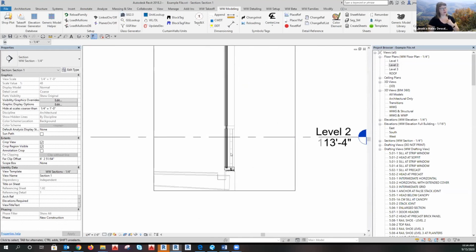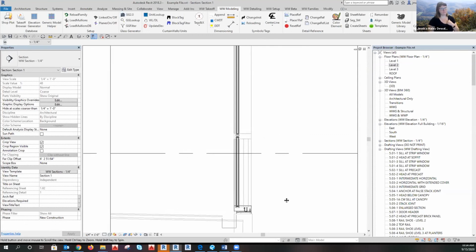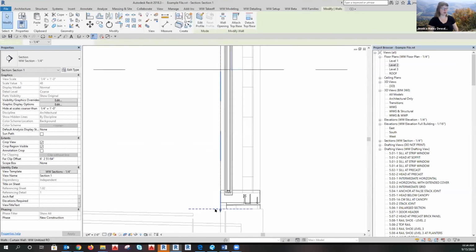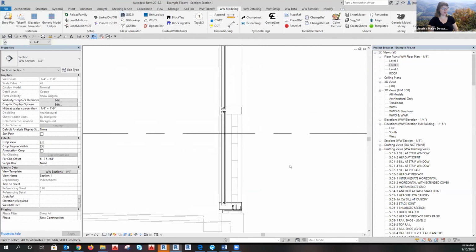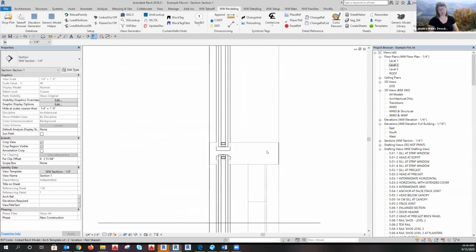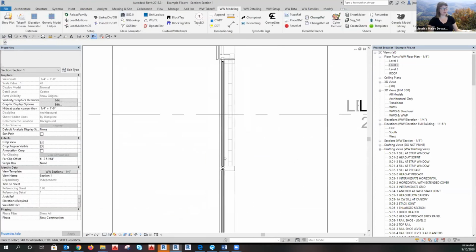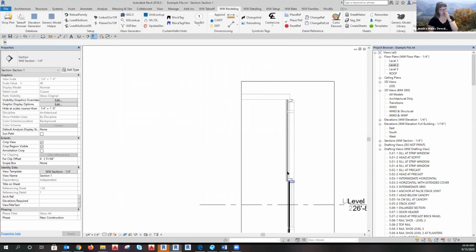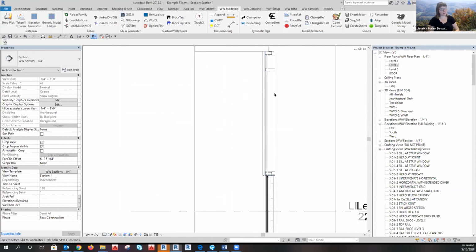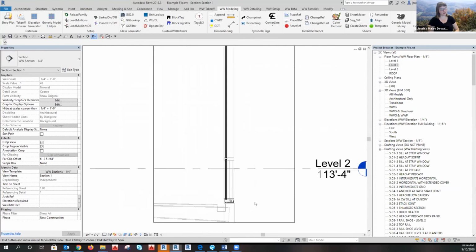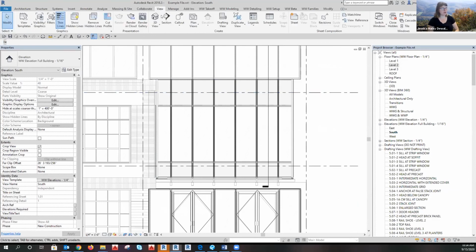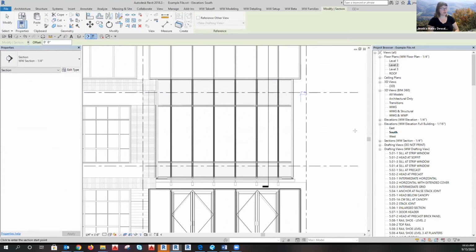And then I will zoom in to my curtain wall to make sure everything looks good. So you can see here is my curtain wall, and like magically now my horizontals are lining up, the face of system is lining up, everything looks beautiful. But we got this weird bit because we haven't done this top part of the wall yet. So after you export, you just want to use live cuts. It'll make a live cut through the plan view.